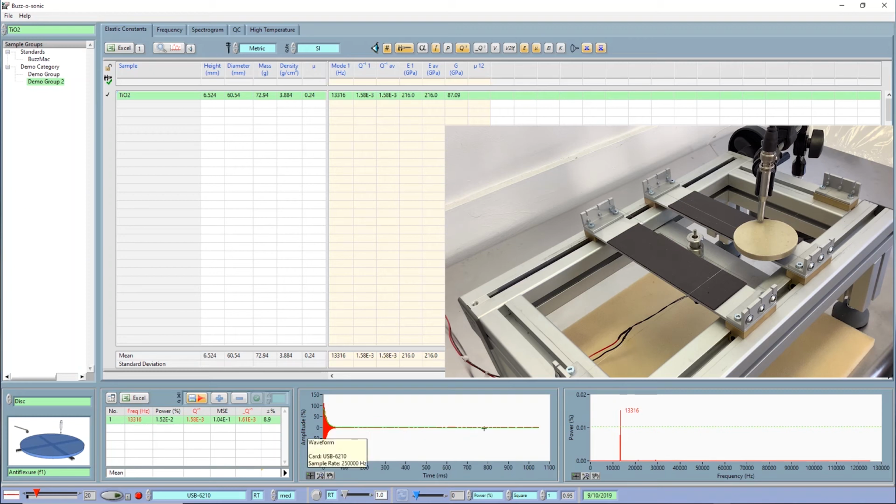So we don't need all this, this is all wasted information. So we can go to a lower resolution if we want. But if we're interested in the internal friction measured by the half-peak broadband method, we should use a 1 Hz resolution. Now if you look here, because it's more heavily damped than the other samples we tested, we see now that these two methods of internal friction are starting to agree with each other. One derived from the log decrement method, or fitting the curve to the waveform, and the one derived from the half-peak broadband method, or the width of the peak in the spectrum. Those two methods are giving us similar results now, with a much lower error on this one.